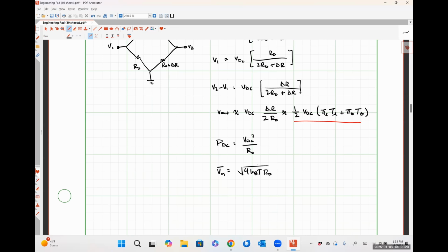The arguable disadvantage here is that we have to be able to efficiently electrically connect this thing with the two piezo-resistive sensors in order to make it work. So this one's trade-off comes at effectively the expense of a more complicated fabrication process.